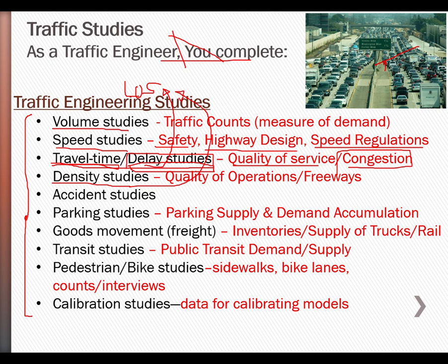Again, I told you before, density is not an easy thing to collect directly. We need to use the word occupancy to indirectly collect the data. So here, the loop detector, probably going to find the loop detector under these cars here. And knowing about the loop detector, you can know what is the density, how much are these cars packed between each other.